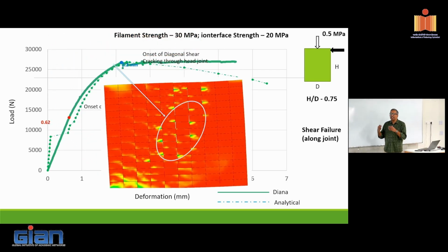So you see what happens with masonry. If I have a masonry wall, subjected to compression always, because a masonry wall will always have some load on top, and I subject this masonry panel to in-plane shear, by understanding the behavior of the interface here, you can essentially predict the behavior of this panel in pure shear. Same mechanics can now be ported to the case of printed elements.